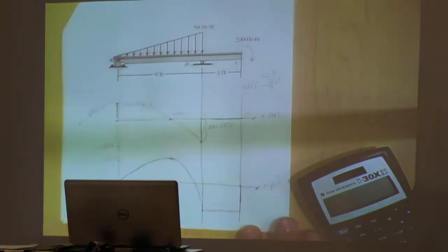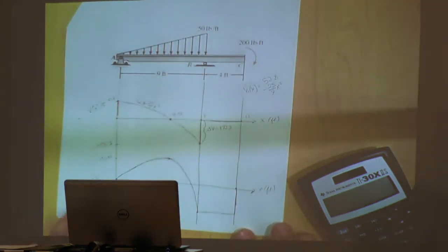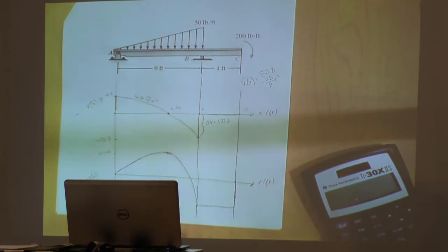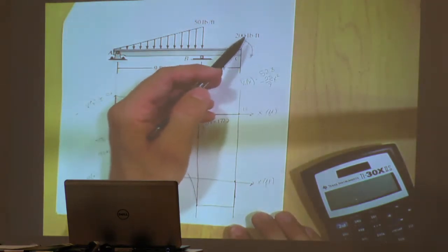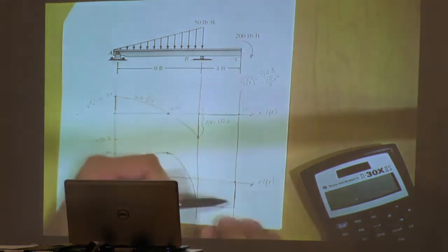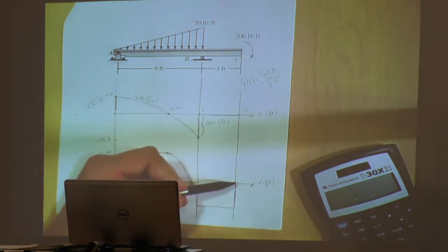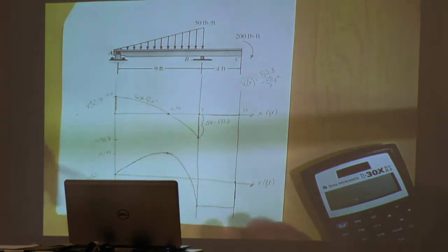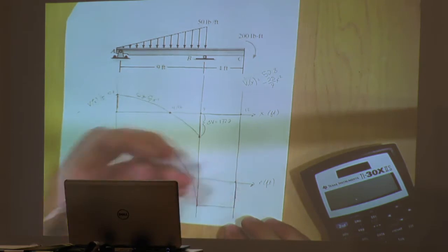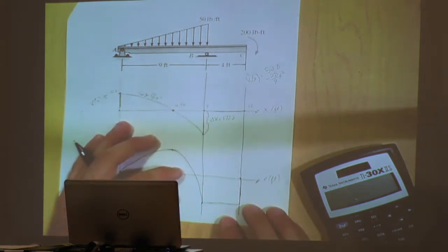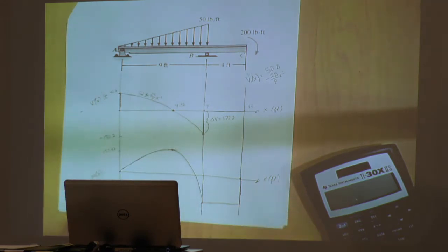I don't believe so, no, because it doesn't really serve us anything here, because we're not taking another integral. But yeah, good question. So on the graph, when the moment is negative, it's counterclockwise. It's a little bit tricky, because using our normal convention, it's a negative moment, but yet we're going upwards. So it's just kind of opposite. I don't know the actual reason behind it, but that's the way to think of it. Since we have a negative moment, just think of it opposite, and it closes it.